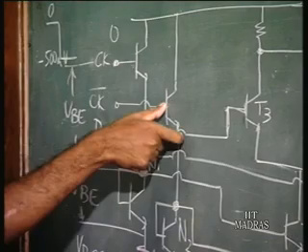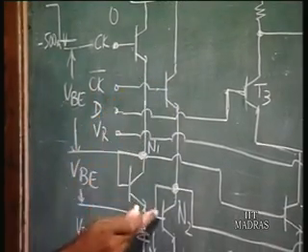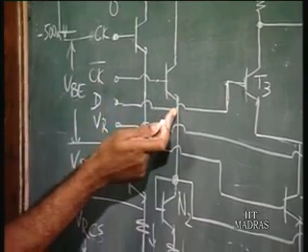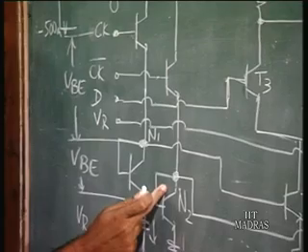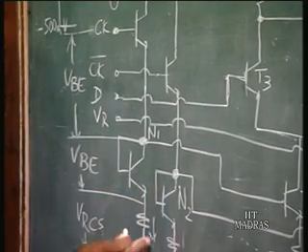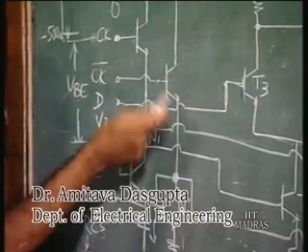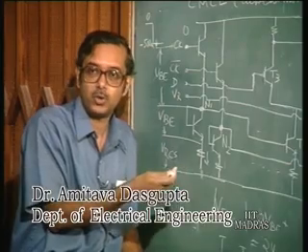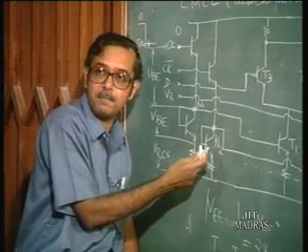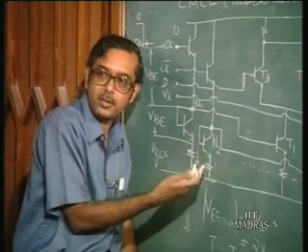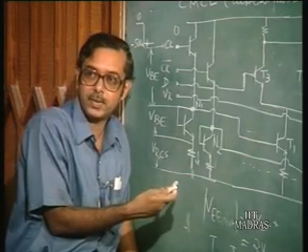Basically, 1.5 volts is going to be dropped between this VBE of the level shifting transistor plus this diode arrangement here. So, the maximum voltage which can be dropped, if both of them are carrying the same current per junction, is 0.75 volts. So, this transistor is going to be off, which is less than the requirement of VBE, which we have said is 0.9 volts.